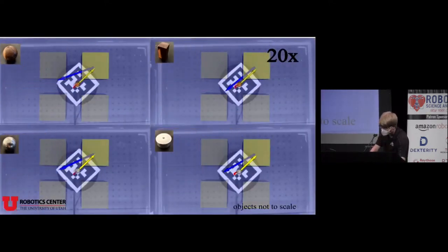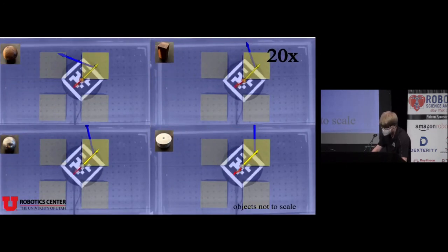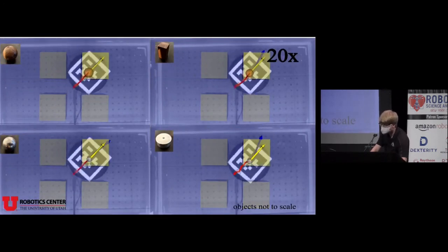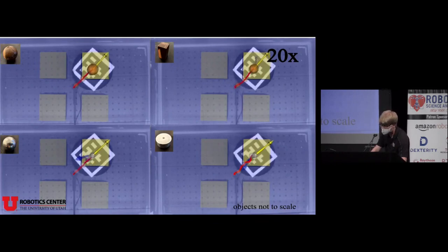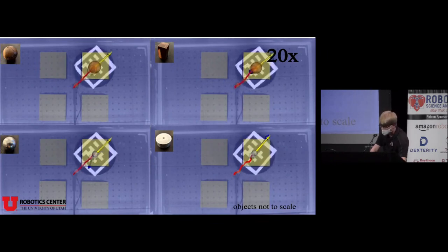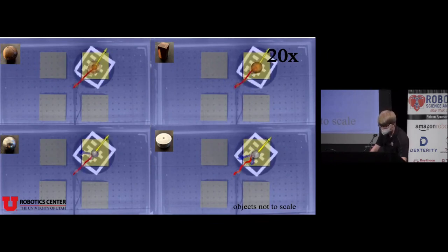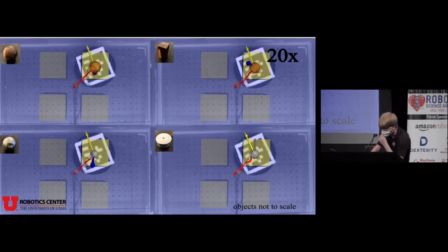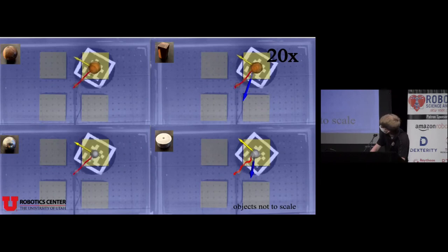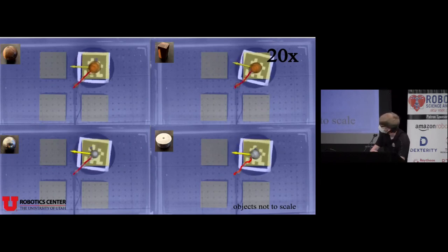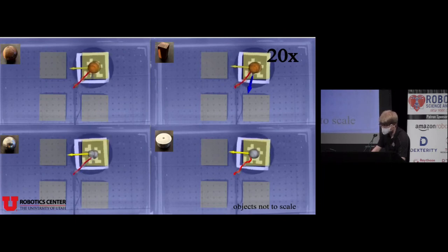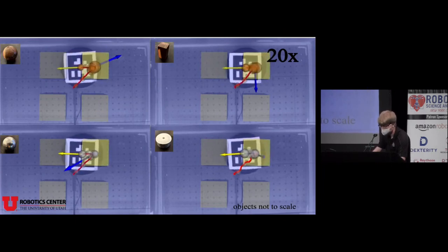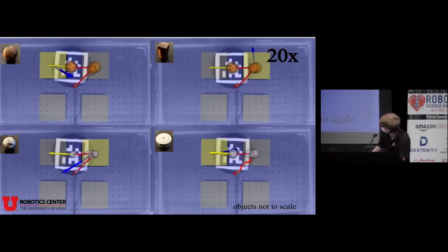Our adaptive controller, building a local dynamics model, enables us to fit our model of spherical objects onto objects that could never be globally modeled as a sphere, and use our adaptive control on spheres and non-spheres alike. It is also interesting to note that all 4 objects here were initialized the same, as a small copper sphere, and the PID gains and PID controllers are identical for all of them. The difference between them is captured in the model adjusting the current estimated object size, shown here as ghost objects.